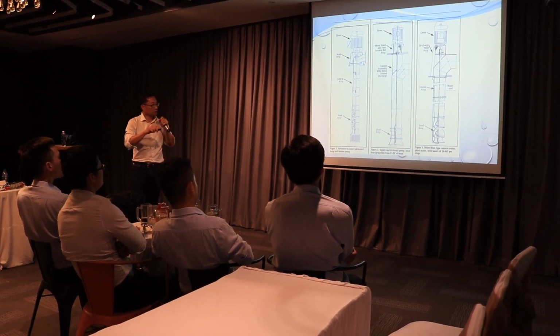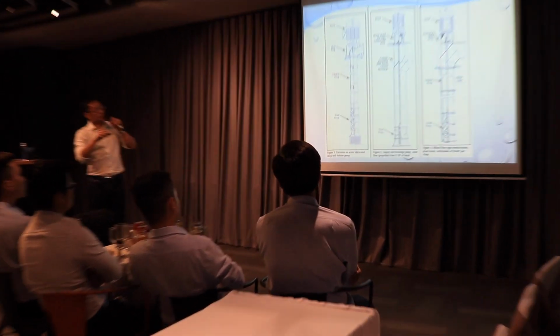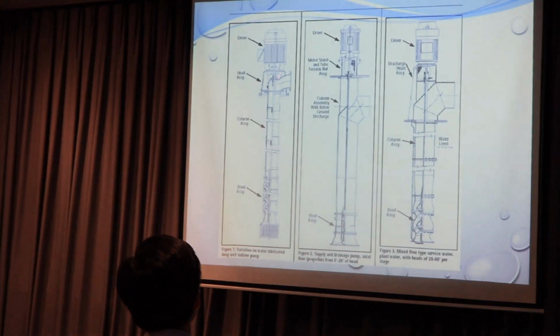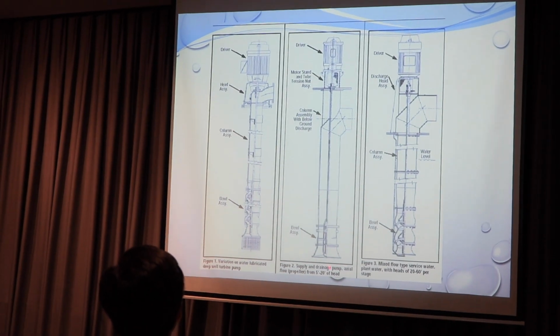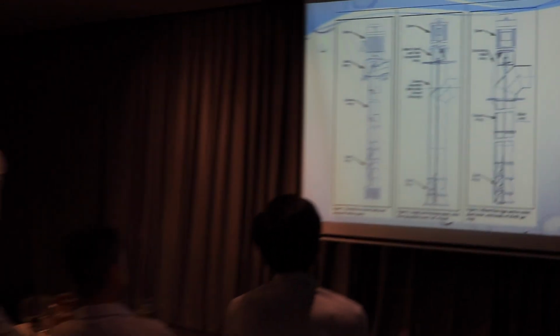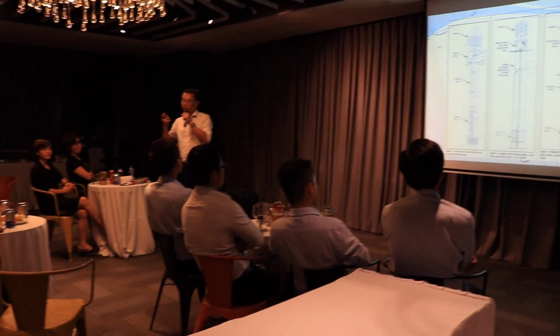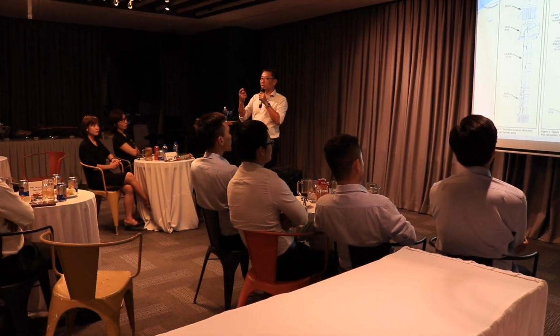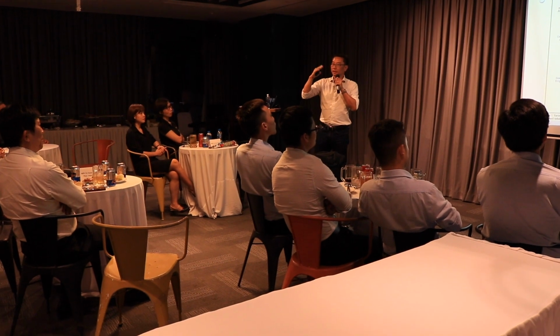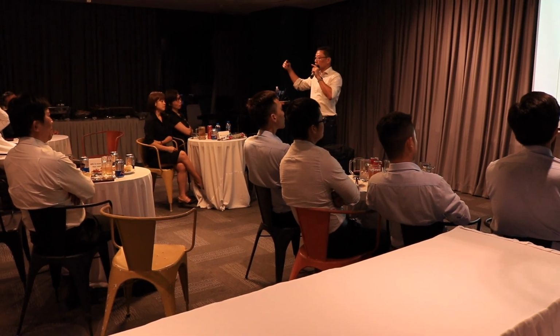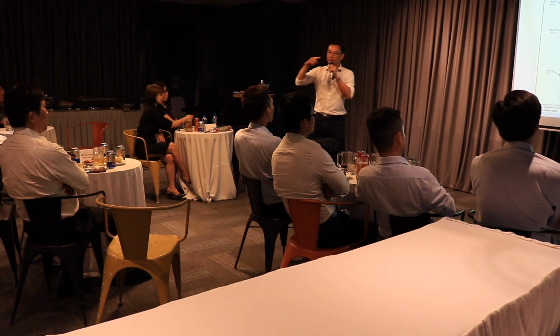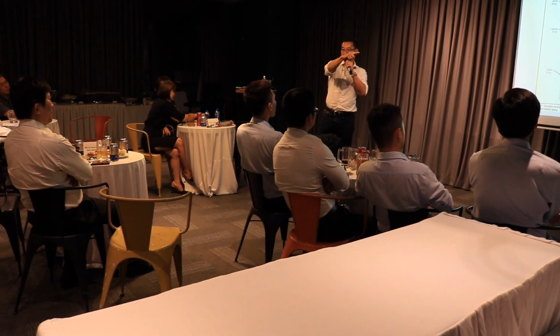This again is a vertical turbine. Again, the discharge, this is above ground, below ground, above ground, vertical turbine, axial pump. All these are different based on the design of the impeller, the shape or angle of the exit. Axial pump, the water goes in, it comes out 180 degrees, the flow.